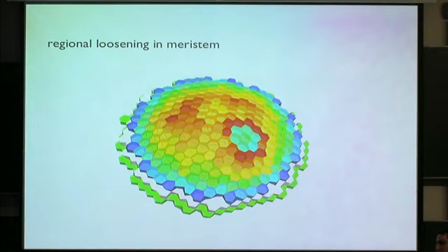You showed initially at the very beginning that you were comparing shell elements versus triangular elements. Have you done any error analysis, finite element error analysis, on these? No, we have compared the results numerically in plain tests and they show a very, very good agreement. I don't have any number in my mind, but they have been really satisfactory. But typically, you're committing errors which maybe you don't with the shell elements, I would assume, and you don't quantify how much you lose when you use triangle elements.